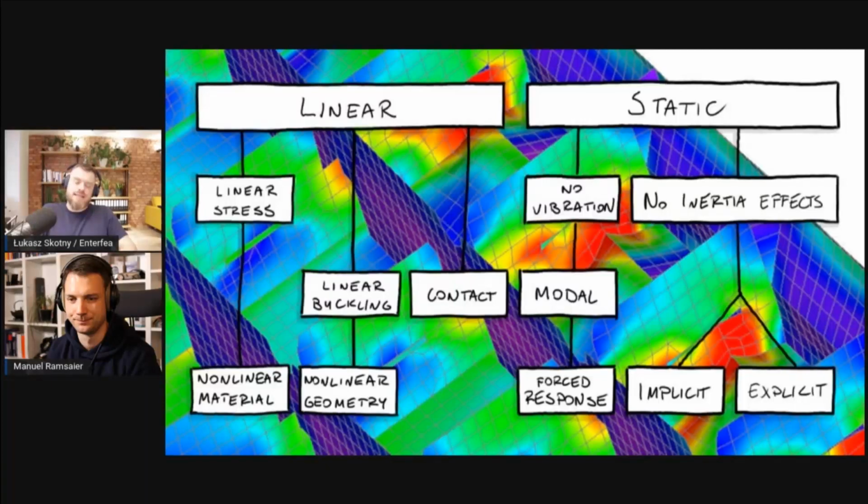And the idea here is, I hope that when I do modal analysis and I get those frequencies for my structure, the frequency of the load I think I will have, let's say that you have a machine that vibrates with a certain frequency and you're afraid that it will start to shake your entire building, right? You just hope that the frequency of the machine and the frequency of the building do not match.